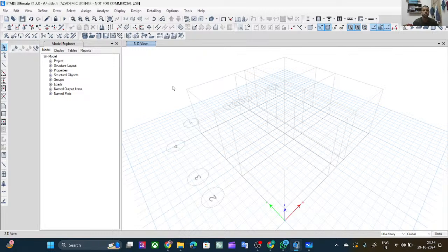Now first, because the height of my building is not very high, the column dimensions depend on the height of the building and depend on the weight of the building. Okay, and we will use the thumb rules of columns and beams, and first we will define the properties of materials. There are ground floor and first floor. So G+1.